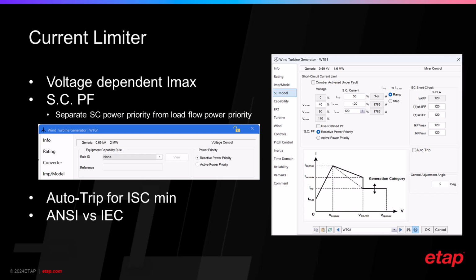So this becomes continuous, and what happens is that if the voltage comes back to the deadband region again, we're going to have a timer, and the timer is not going to expire until a preset time after coming back to the normal case. So let's say that the timer by default is 100 milliseconds, and the voltage goes below 0.9, and then we start injecting reactive power, and the voltage comes back above 0.9. We're still going to inject for another 100 milliseconds reactive current according to the FRT. Now, this is what happens in dynamics.